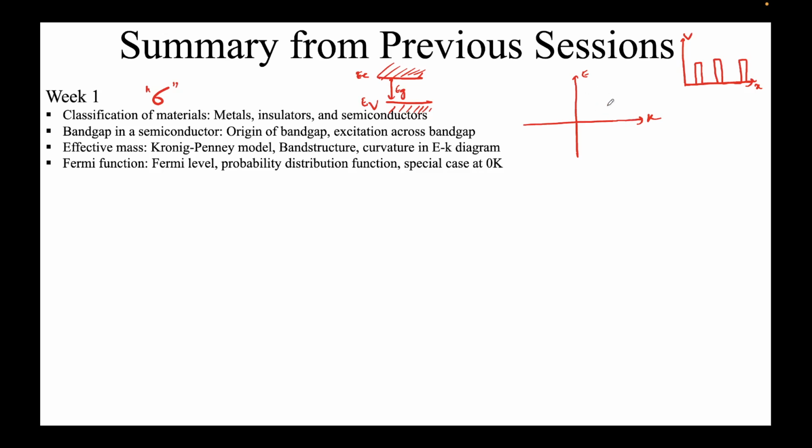We demonstrated it in terms of the E-k. The energy versus k, where k is a wave vector given by 2 pi by lambda, and we saw that the electronic energy now can be written. This diagram, by the way, E versus k, is the band structure. Again, the conduction band energy EC and the valence band energy EV, and again you see the difference between the minima of conduction band and the maximum of valence band is the forbidden energy gap EG, and here there are many states in the EV and also in EC.